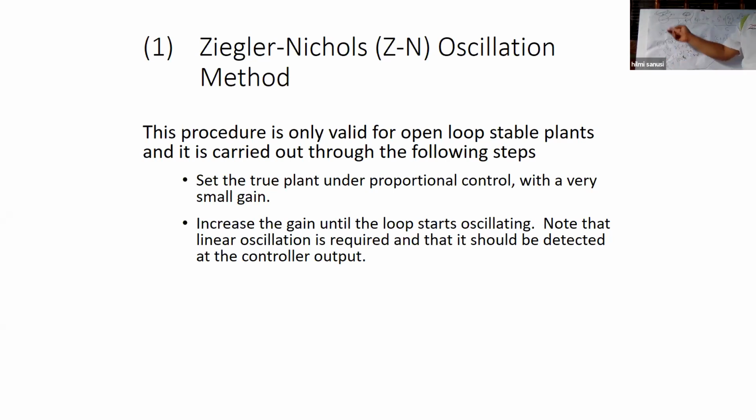We have to tune our PID based on loop shaping. We look at how big the phase margin is, how big the gain margin is, and we make sure that the gain response I showed earlier must be within the system's frequency response.